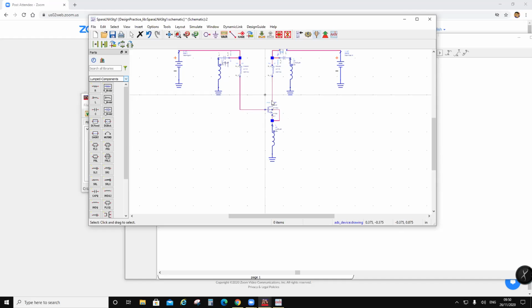And at high frequency, this becomes very important because the source inductance cannot be large. If it is large, there will be no gain at high frequency, right? So the source has to be grounded properly with many wires. Now the question is how many wires? Okay, so let me just go to a place where I can write.